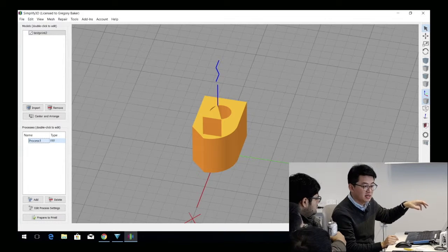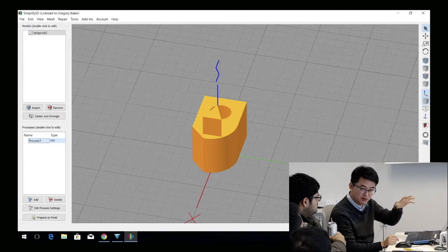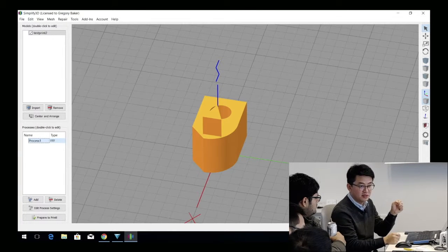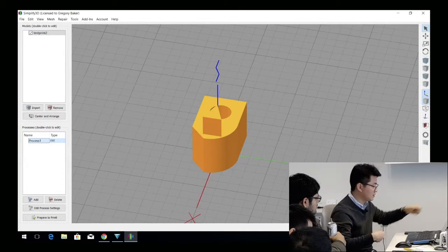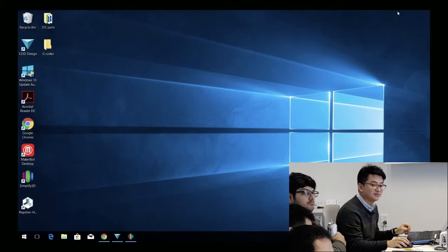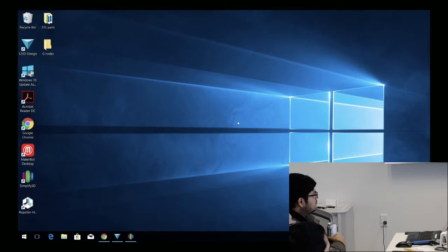Once you've done the printing, the bed will cool down, but before it's totally cooled down, you just wait a little bit, make the printing result solid enough, and then you peel it off. At that moment, if the temperature is still above 40 degrees, it's really easy to peel it off. Use your hand. Don't use any tools. It will scratch the heat bed easily, and the next printing will be really messy. Okay, so that's a really big problem with 3D printers, is people go in with some sort of tool. Oh yeah. And it just really ruins the bed. So you have to be very careful.